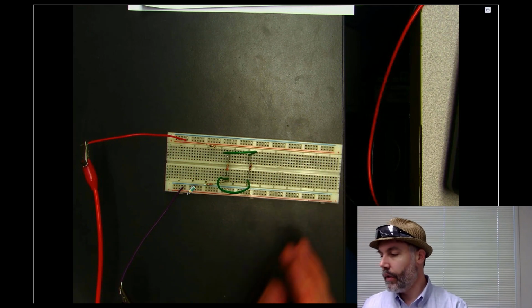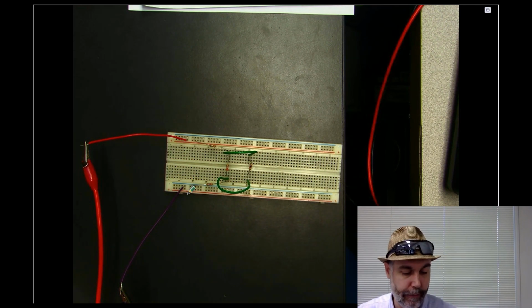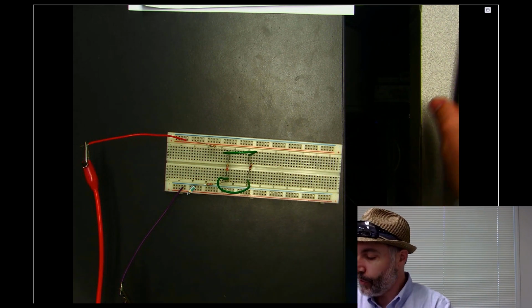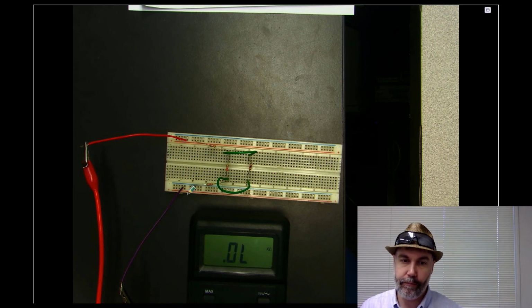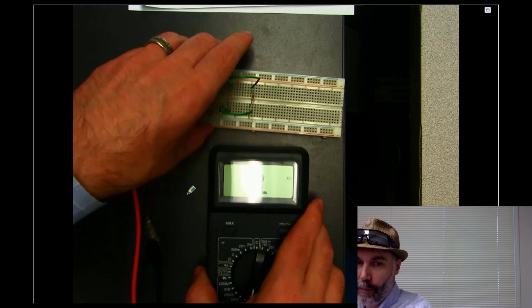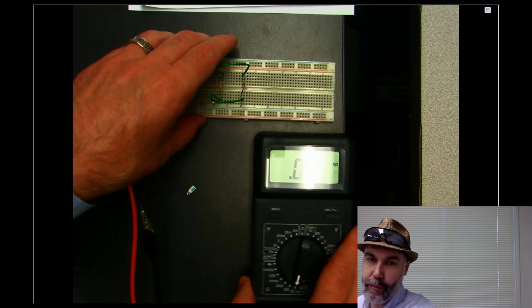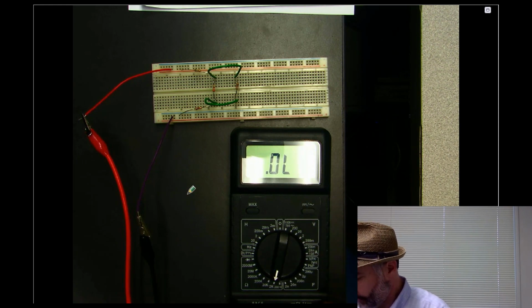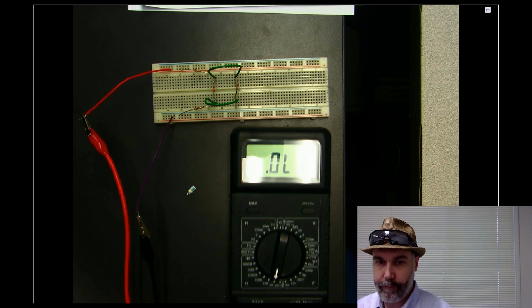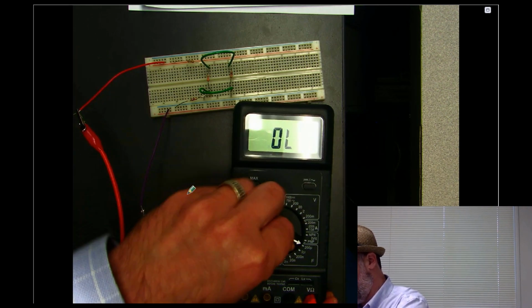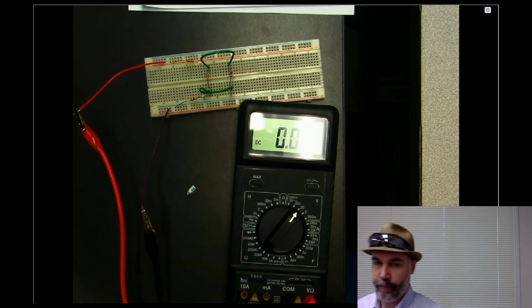And now we're going to make the measurements for this circuit. So we're going to measure the voltages and the currents for each resistor. Okay? So first of all, I'm going to measure the voltages. So I'm going to put the meter into voltage measuring mode. I'm going to leave the red lead in the right-hand port, and I'm going to turn the dial over into the voltage region.